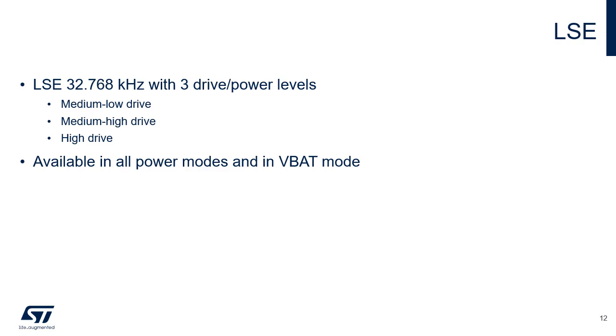The LSE also offers a programmable driving capability, which can be used to modulate the amplifier driving capability. 3 modes are available: medium-low drive, medium-high drive, and highest drive. In case of an analog clock, the LSEBYP and LSEON bits must be set to 1. In case of a digital clock, the LSEBYP and the LSEEXT bits must be set to 1, followed by setting the LSEON bit to 1.